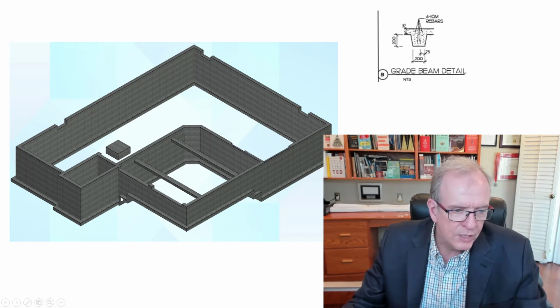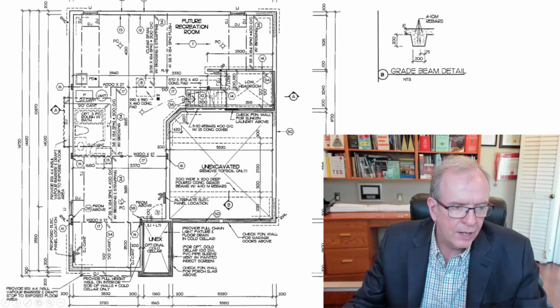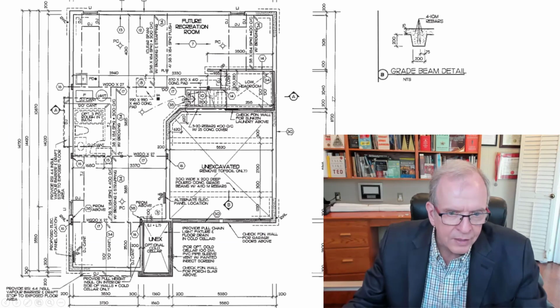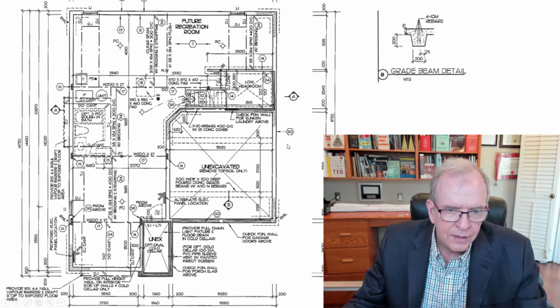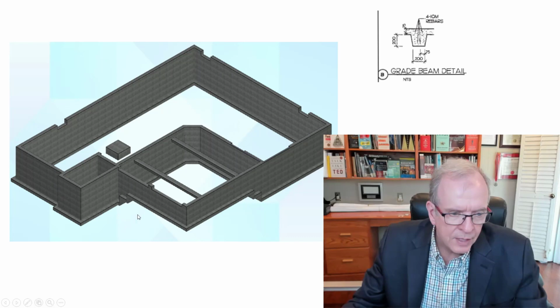So we want to make sure this area here is cut and stepped in so that it is on undisturbed soil. So that's that little spot in this connection point here, and that's the spot over here that we're looking at. So when I say that, that's there, and when I say this, that is here, and that's your connections, and that's where your footing is stepped.